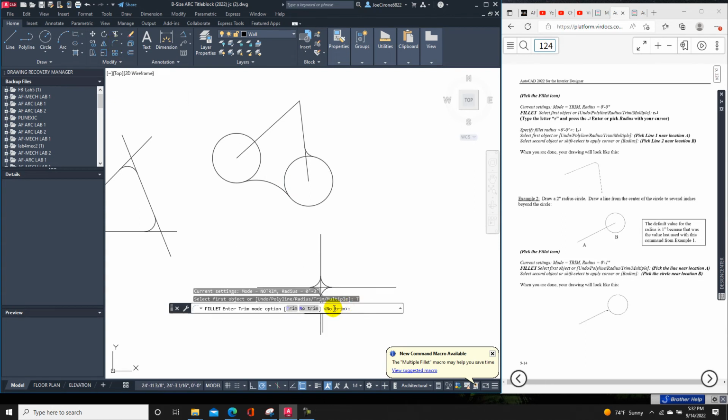If I turn the fillet trimming on, so I say trim yes, and then I go through and fillet it, it will cut the circle as well. Well, maybe not. But you can always trim it the old-fashioned way with just the regular trim command, and then as long as the geometry is between bounding object shapes, you can trim that out.